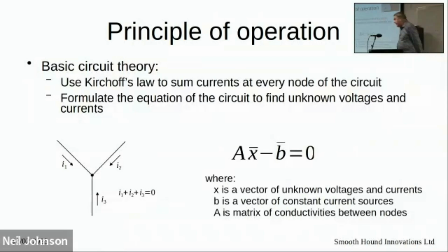So I went about designing a circuit simulator, and I called the system MySpice. I actually stumbled across how Spice worked myself, and thought I'd been very clever, and then realized that's how people have been doing it all along. We start off with a bit of basic circuit theory. We use Kirchhoff's law to sum currents at every node in the circuit, and formulate the equation for the circuit to find the unknown voltages and currents. All looks very, very simple.